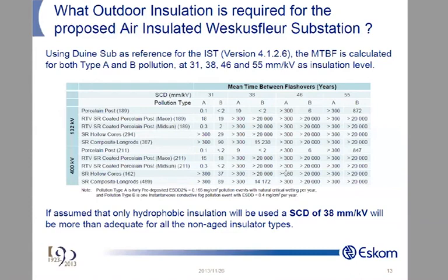There's another question. Yes, sir. I was going to ask whether the application of that silicone could be retrofitted to an in-service insulator, or is it a manufacturing process, or something you just paint on yourself? Oh, the rubber, you mean the coating? No, you can do it yourself. The guys can train you. There are different application techniques, and you can do it very well yourself.